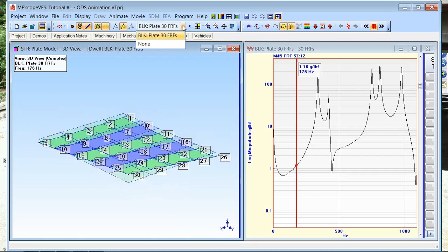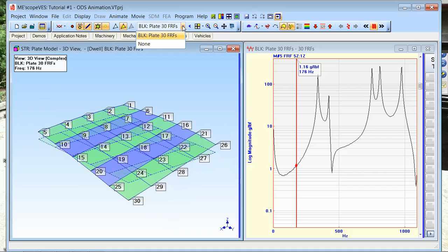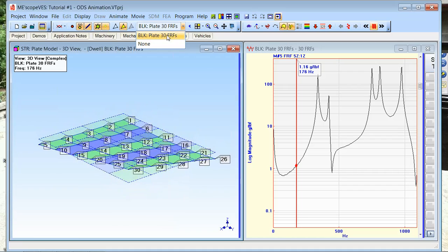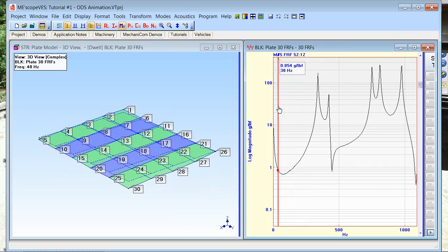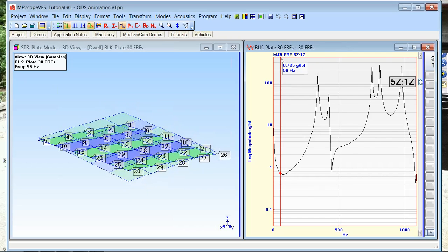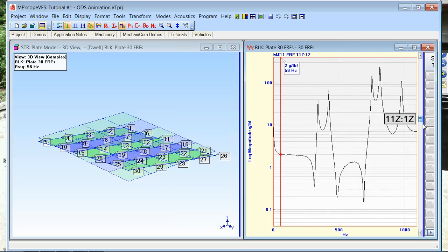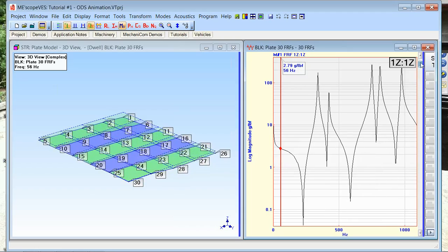The piezoelectric accelerometers that we use go down close to 0 frequency, but they don't actually measure right at 0 frequency, typically. Now, there's many different types of accelerometers. Some of them will measure DC motion. In this case, the one we used had a little bit of error in it, but that's still an indication that I've got good data.